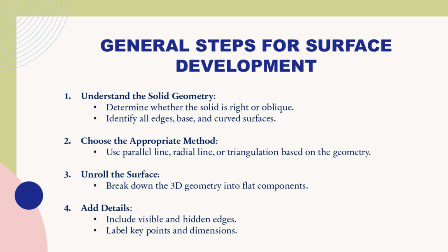Surface development follows a systematic, step-by-step approach. First, carefully understand the solid's fundamental geometry. Determine whether the solid is right or oblique in its configuration. Identify all critical edges, base, and curved surfaces precisely. Choose the most appropriate development method based on the object's characteristics.